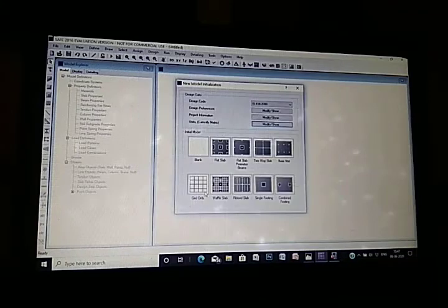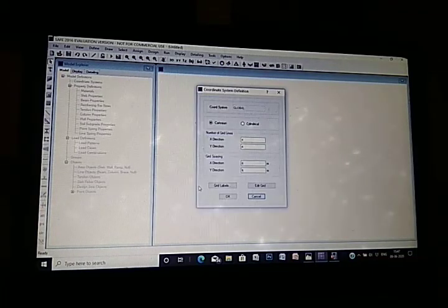Click on OK. So we will use a grid. So next, so there are 18 meter. So we will make 19 grids in both directions, x and y direction. So each grid spacing will be 1 meter.